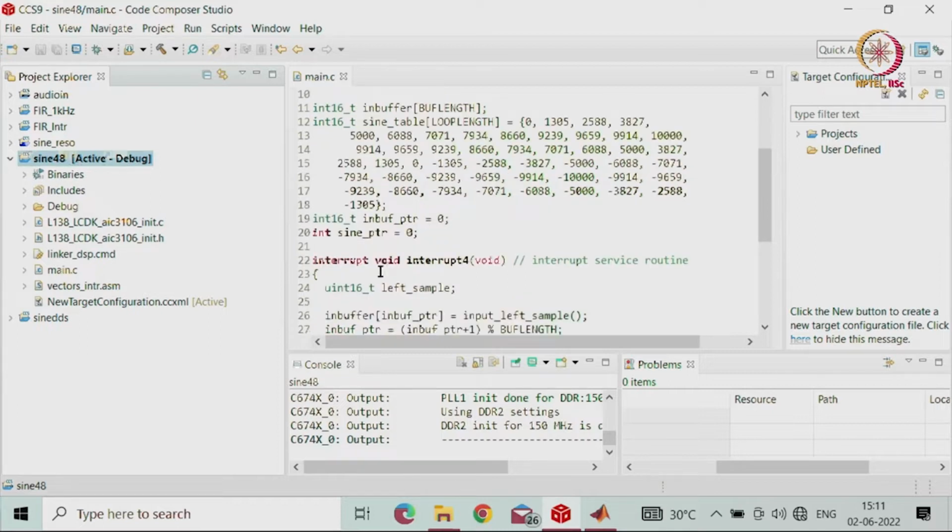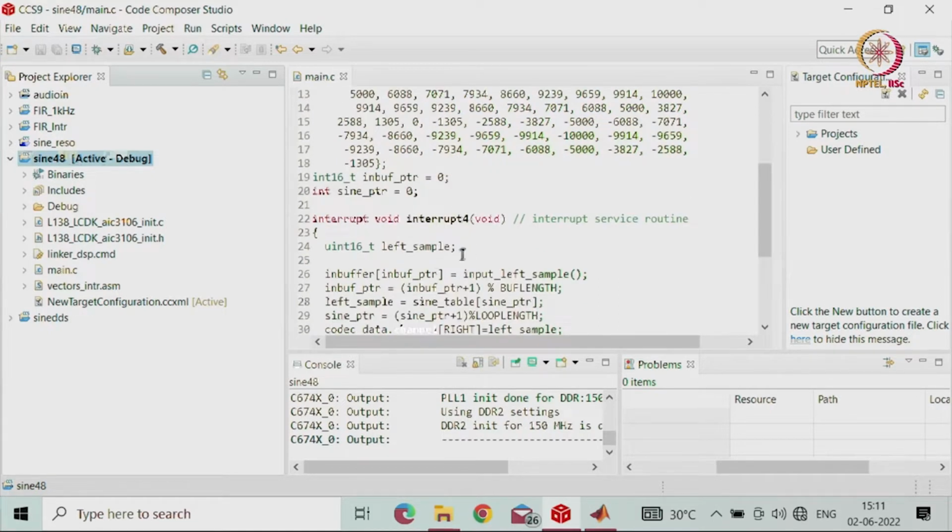So, here we are going to do interrupt driven. In this case interrupt 4 is going to be used and then you will be getting the stereo data. As I have mentioned in the first lab session, we can have mono input or stereo. Whenever speech is there, either we can take it from the mono, that is a mic we can connect, or we can connect the audio input from our laptop. Today we are connecting the audio input to the board.